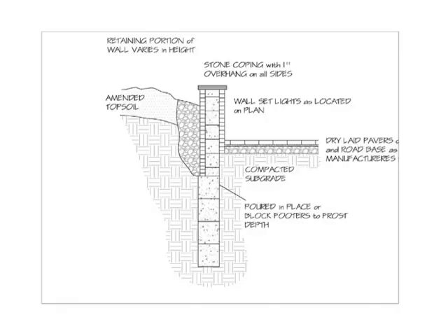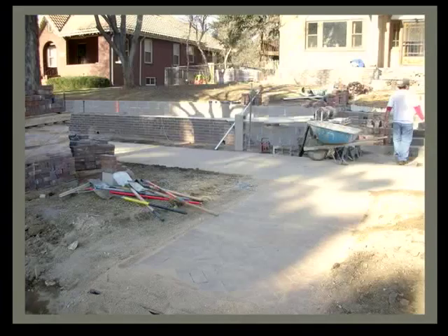Here's a construction detail that shows how we're going to build walls on that site. So this is a concrete wall that is veneered with brick, and I'll show you some construction pictures. To make that wall work, brick doesn't hold things up. You need concrete, and the concrete to hold things up needs to go below grade. And that drawing doesn't show it, but it should have rebar in it, and it might even want to have a spread footer, like a T at the bottom. So this is how the concrete works.